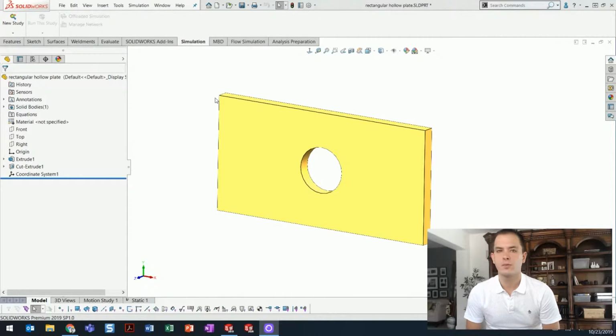So let's just get started with the most basic type of simulation, a structural FEA, what we call linear static analysis. All that means is it's just very simple. A simple material being used, something very common like aluminum or steel, and it's a single part. Okay, so let's just talk about how we set this up, how we perform a study using SOLIDWORKS Simulation.